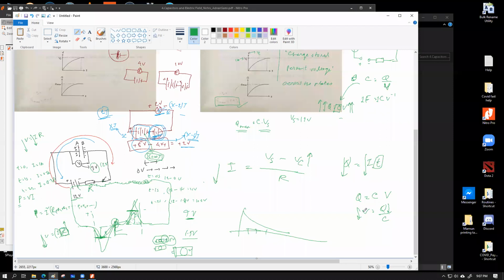Yes, sir. So you are going to have a gradual decreasing effect, which means the further your capacitor becomes charged, the more opposition it provides, which reduces the current, which in turn reduces the amount of voltage gain, and that reduces the amount of reduction of current value as well. So you're going to have reduction of current, but you're going to have that current reduction more leniently further down the line.